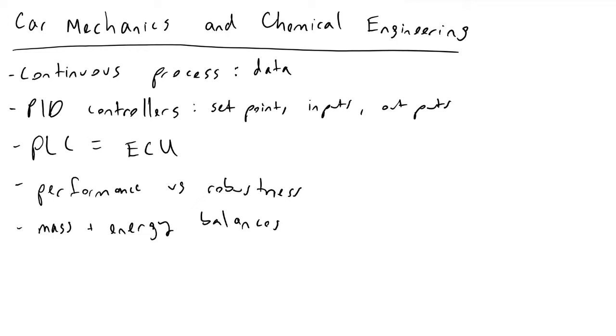Based on the oxygen present in the exhaust of your reactor, or engine, the ECU is going to adjust the amount of fuel it's spitting into your air fuel mixture. If you have a very low concentration of oxygen, that means there's way too much fuel, and therefore your ECM will tell the injectors to dampen the amount of fuel they're putting into the intake.